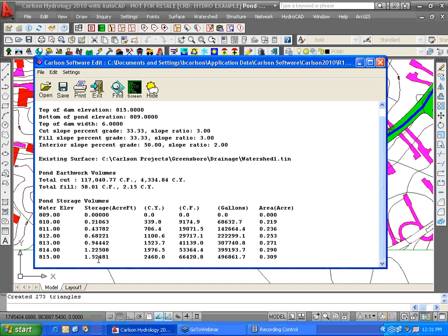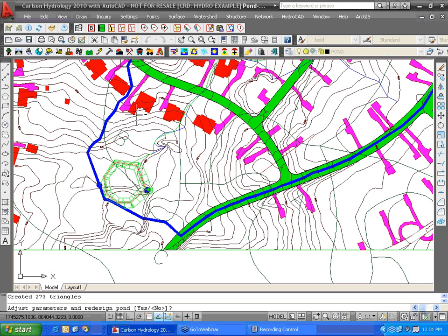And for those designers out there, it's a real challenge to get your spillway design such that the minimum pond it recommends works. I like a little margin, so I'm going to go to 1.5 and avoid the precise 1.4 absolute minimum size that could possibly work with the best spillway design imaginable. There are your volumes, and I'll hit exit.